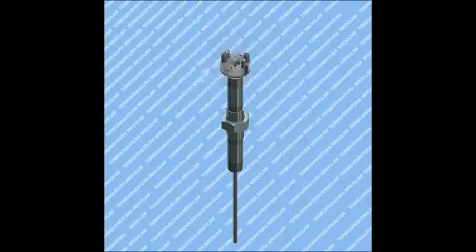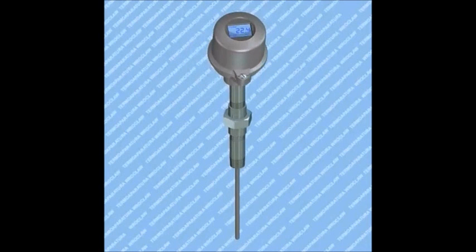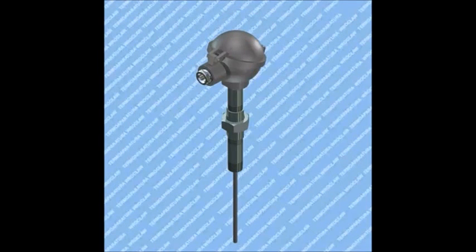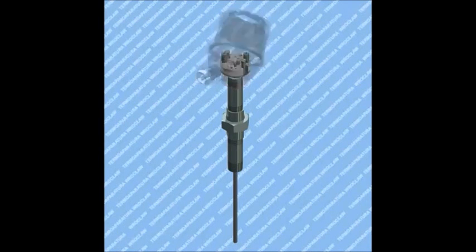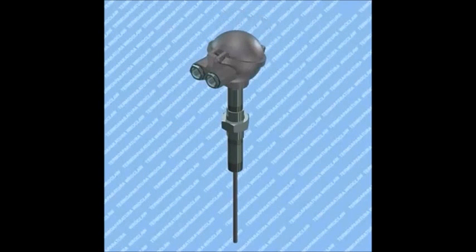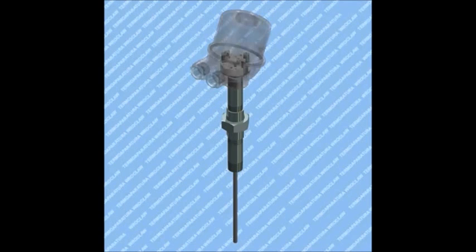In order to make the controlled variable accessible to the controller, it must be measured by a measuring element. This can either be a sensor or a thermocouple. The measured value is then converted into a physical variable that can be processed by the controller as an input. This measuring element may also exhibit a dynamic lag. For this example, our measuring element is a thermocouple, or any temperature measuring element.